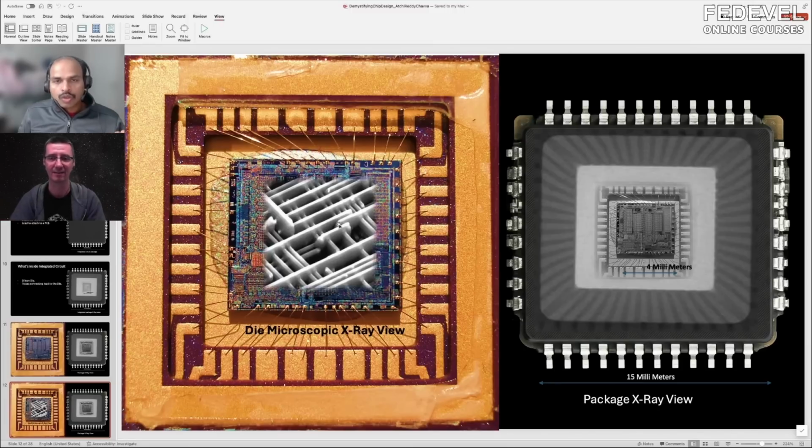Even crosstalk, if you look at it, is made out of a basic building block, a CMOS transistor. The CMOS transistor has two structures, what we call a PMOS and an NMOS. Each one has its own doping levels. So we do consider what the doping levels are and what the spread is. What is the coupling capacitance between those devices and structures based on the area, thickness, and width? Yes, they all play an important role.